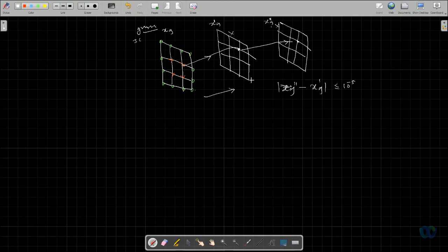You got it? Yes, I understand, but what I'm saying is that the difference between the last iteration and new iteration will be the same as the residual, right? We are already checking the residual. No, residual is different. What we are doing is, suppose we are calculating interior points. Now, suppose you are at this level. I'm calculating this point's values, and this point's values.